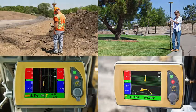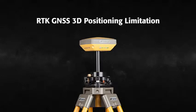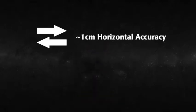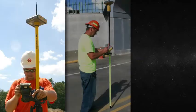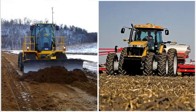Using RTK GNSS for precise three-dimensional positioning does have a minor limitation in that, because all of the satellites are overhead, the receiver cannot resolve vertical positions as accurately as the horizontal. Typically, where RTK provides horizontal accuracy within a centimeter, the vertical accuracy is within approximately 2 centimeters. Today, RTK GNSS is the most common form of precision GNSS technique used. RTK GNSS is the heart of a single operator collecting topography information or staking construction points, and is the key to machine automation in construction and agriculture.